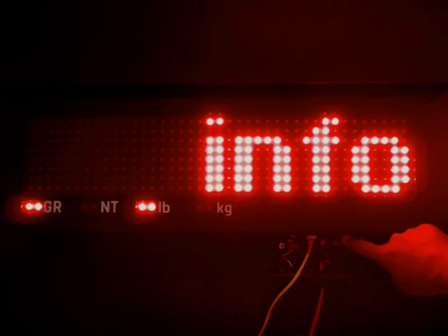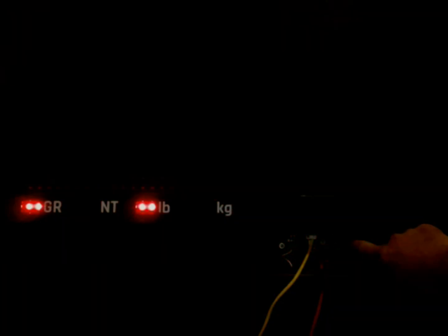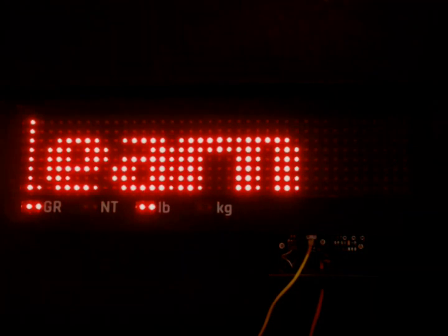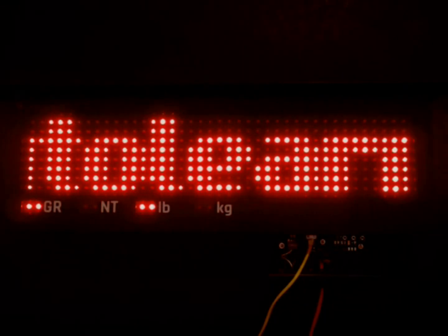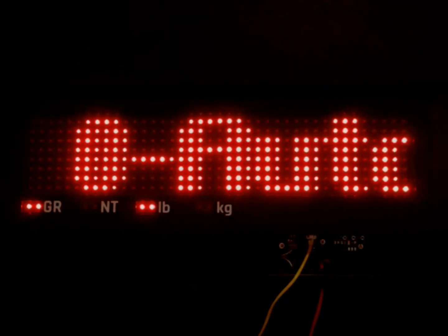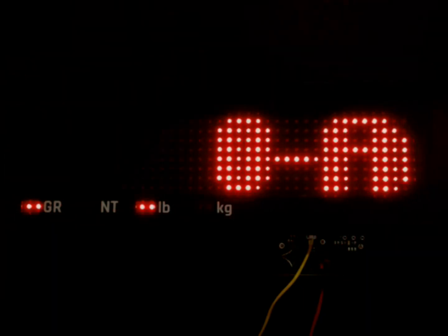Next, we're going to manually set up the protocol. Hold the left micro button until you see Proto. Let up on the button, and you'll see the current protocol setting is 0 Auto Learn. Protocols 53 and 54 are for the B-TEK string. So let's continue to press the micro button until we reach 53.